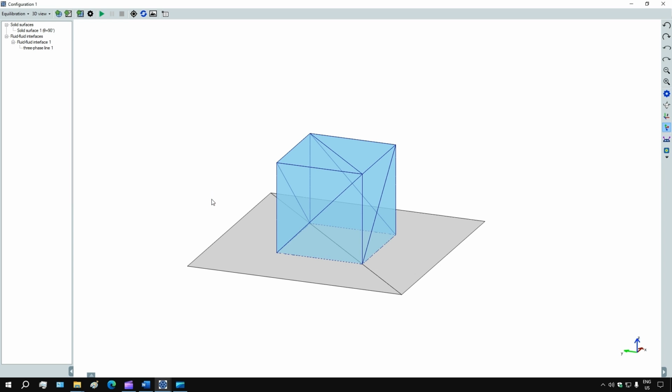Once a valid constraint is assigned to each boundary, it is possible to launch the equilibration. That is, the simulation to calculate the equilibrium shape of the fluid-fluid interface. As a matter of fact, the Start Equilibration button is now enabled. You can also see that the boundary node in the tree diagram is no longer in bold font, to indicate that a valid constraint is selected for it. Before clicking the Start Equilibration button, let's save the current configuration, for later convenience.